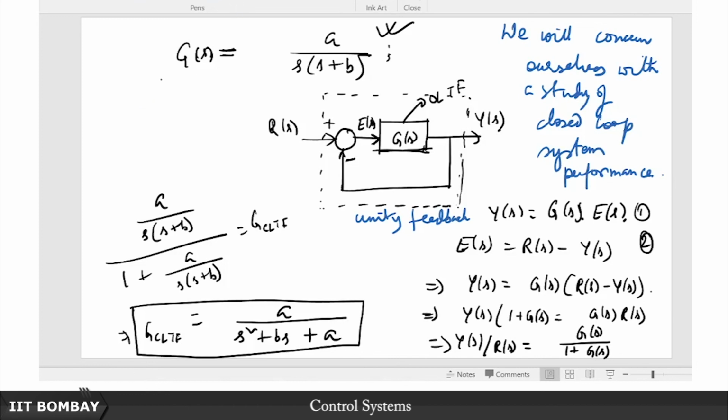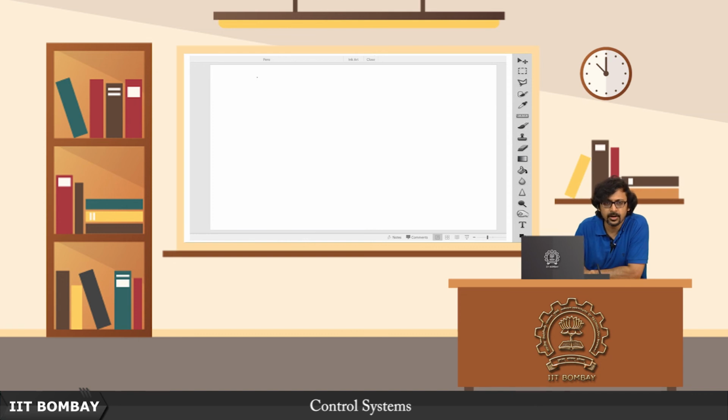For now, the reason I started discussing this topic is that often it might so happen that your open loop transfer function, and this is very important, remember subsequently when we design controllers or wherever it is applicable, always remember this. Since we are already discussing additional poles and zeros, you might have a transfer function that looks something like this: omega n squared upon s into (s plus zeta omega n), into (s plus 1 by tau 1) into (s plus 1 by tau 2), into (s plus 1 by tau 3), something like this.